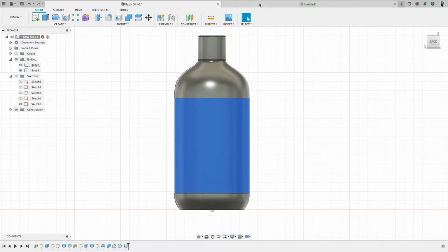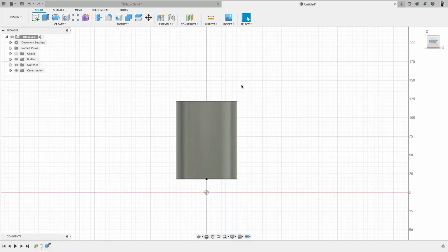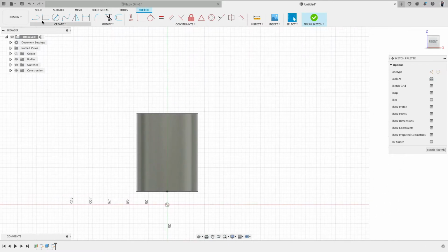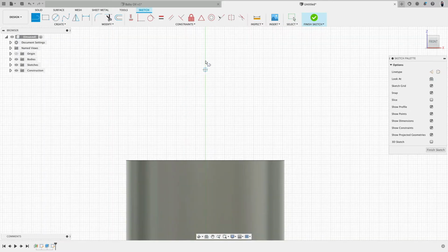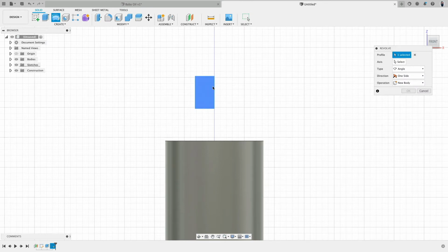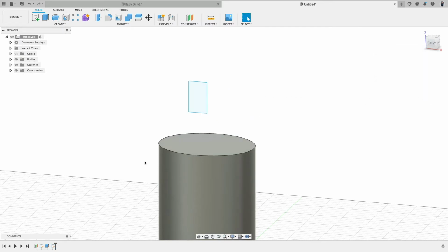The next piece I will do is actually the top part. So there are now two ways how we could do this. From here to the start of the cylinder should be a distance of 42 millimeters. So I could make a sketch, and then I know somewhere here I need to have this rectangle, which then I could revolve. That's all good. That's a doable way, possible.